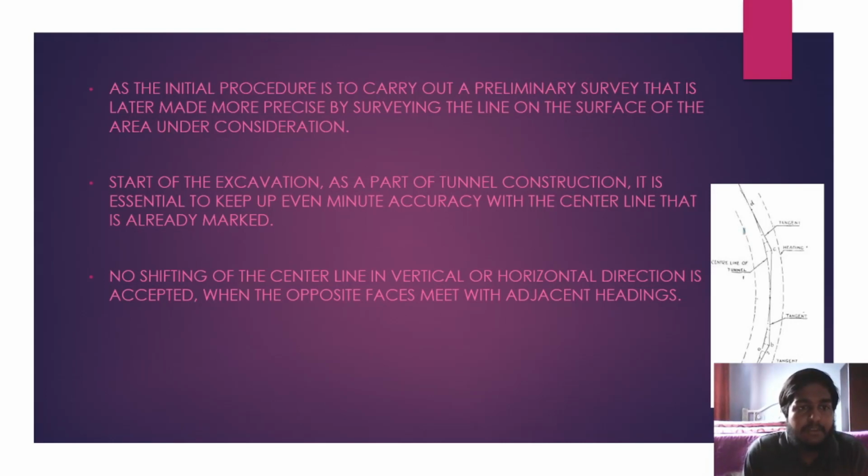The steel tape used for measurement must be checked for errors due to any cause, such as tension and temperature changes. This diagram shows the alignment of the curved line on which construction must proceed. The center line of the curve in the figure is the alignment through the center of the tunnel. This curve must be determined. The headings consist of short tangents drawn to the curved line: AB, BC, CD, and so on.